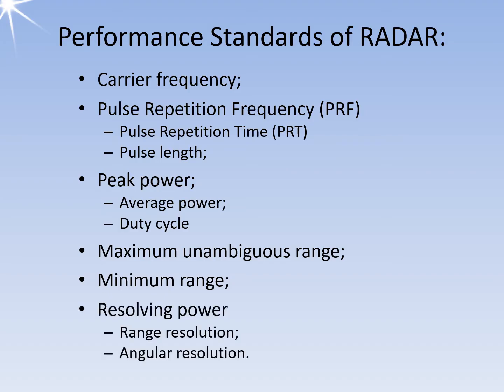Resolving power is the capacity of radar to resolve two objects that are close together. A distinction is made between radial resolution, the range resolution, which depends on the transmit pulse duration or the transmit pulse bandwidth, and lateral and elevation angular resolution as parameters of the antenna.